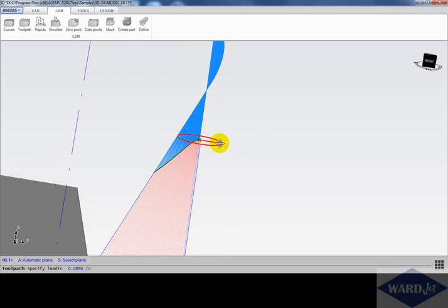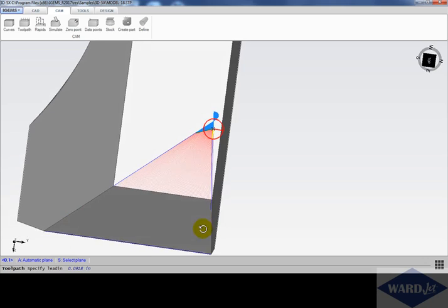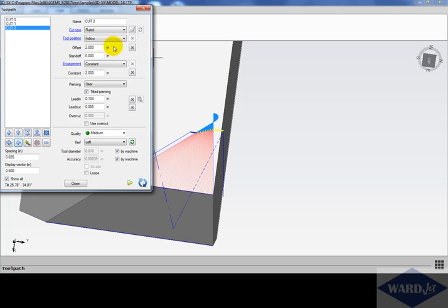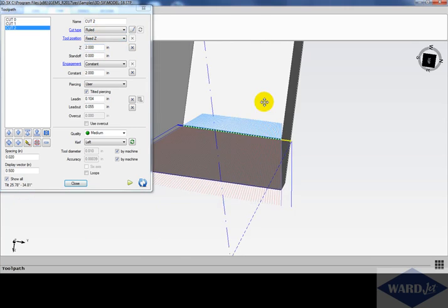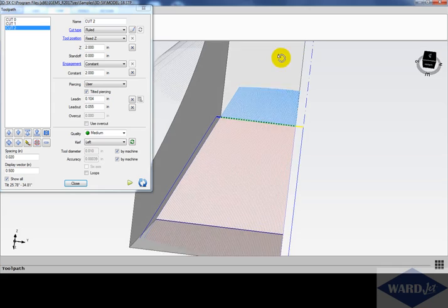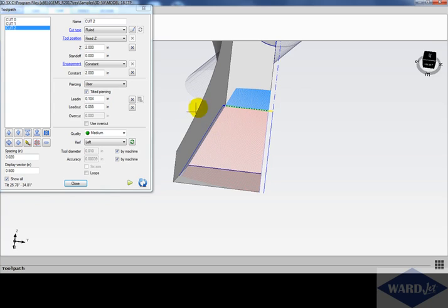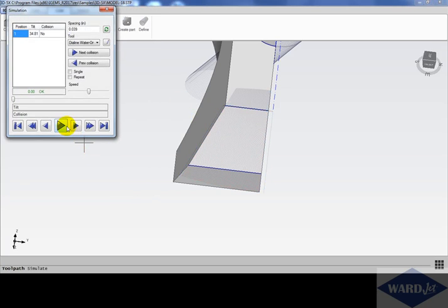And right now this is looking a little bit funny, but that's because I've got the follow set to 2 inches off the material again, but we'll just change that here once I get this added. So lead in and a little bit of lead out here. So right now we'll keep that as ruled, and we'll keep that as follow, or we could change it to fix Z, and then that'll bring it down to the top of the model. So you see the cutting head will start out straight, and then as it's going through the cut here, it'll be tilting over slightly to give us that edge there. And then we can hit simulate again.